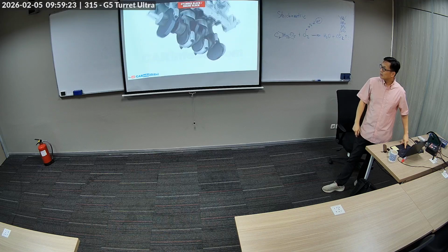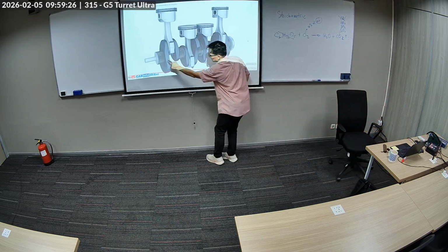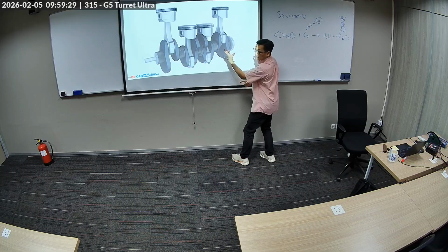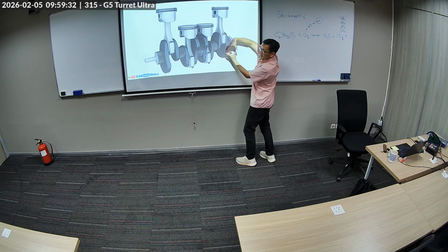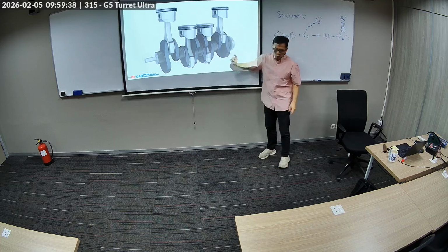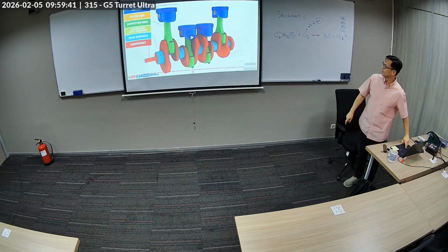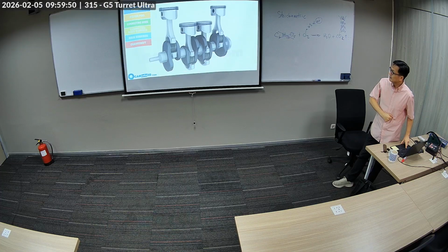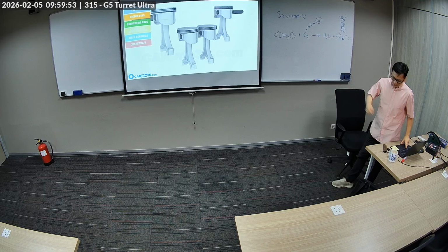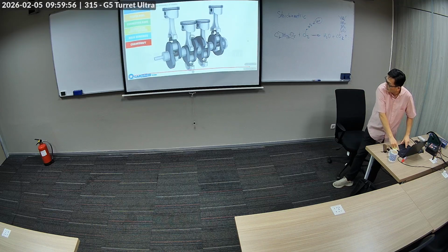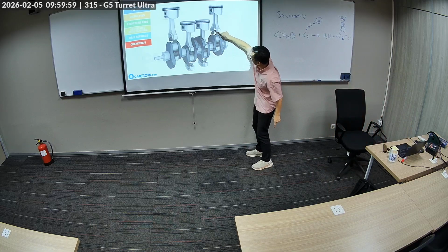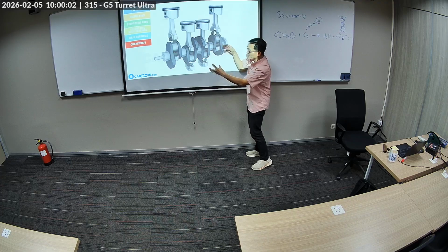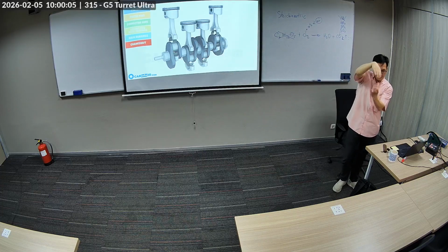That's the main bearing. It holds your crankshaft, you see? So these are the bearing points. The bearing cap and then the housing of the engine block. Okay, so it's captured. But you got that hole for the oil flow. So the blue ones are the main bearings. So that's what I said. They are semicircles. So you have the rod bearings, you have the main bearings. They're all like split halves, circles like that.